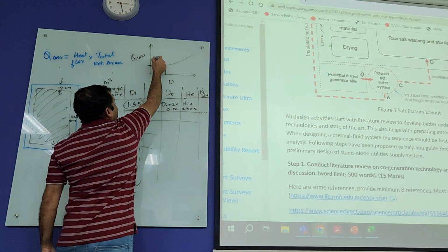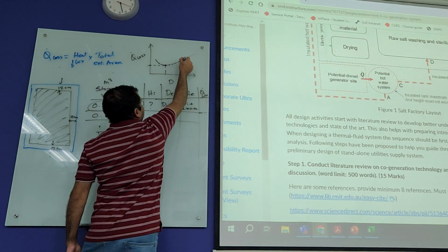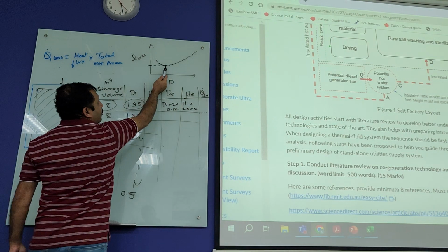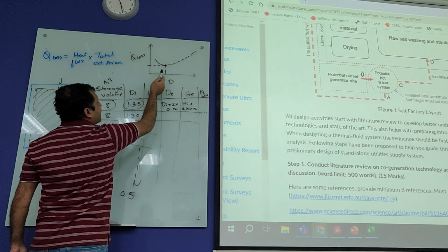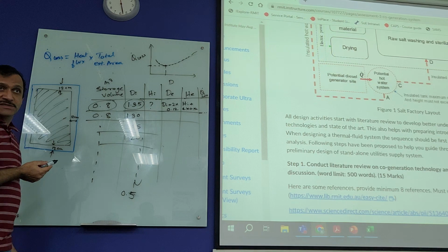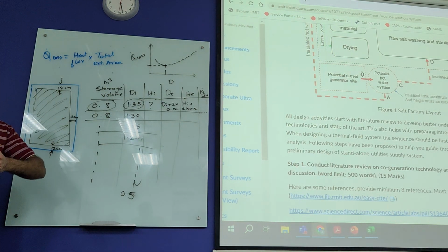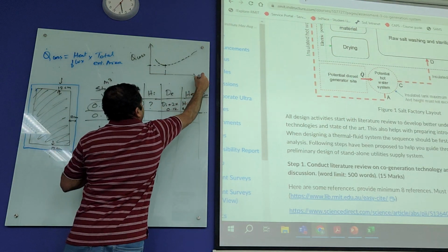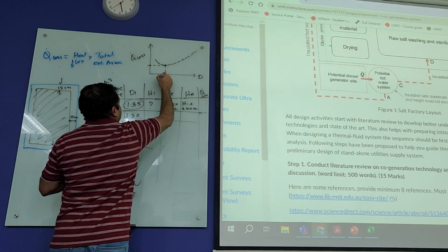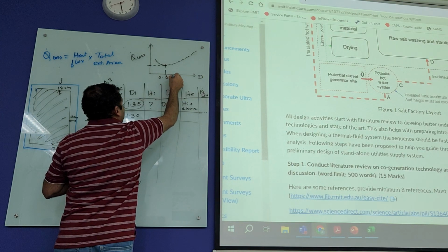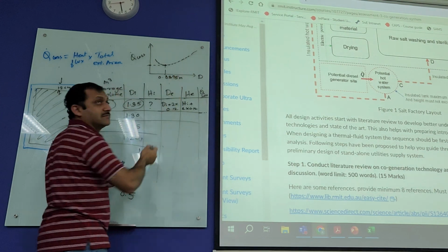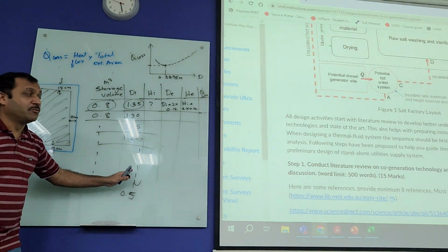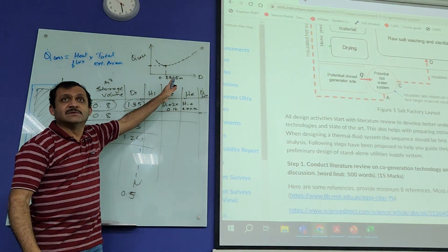And you would get, the heat loss starts somewhere high and then goes down and goes high again. Then what you're doing is optimization. This is the optimum diameter at which you have got a minimum heat loss. Now in the real world, practically, let's say you come up with a diameter of 0.8395 meters. Some number, okay? Somewhere you come up with an optimum, which is such an odd number.